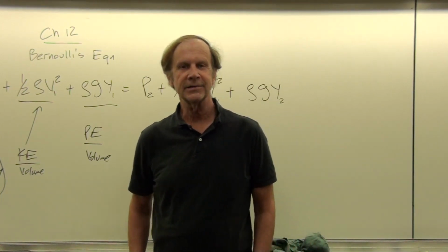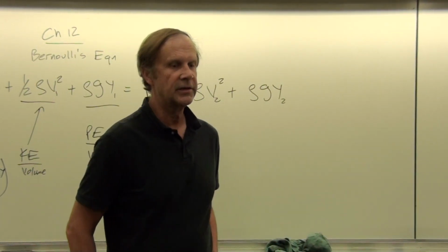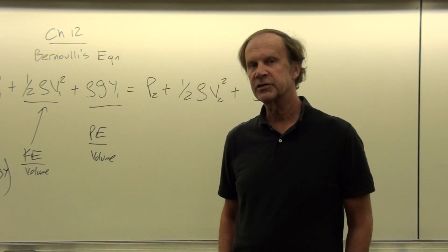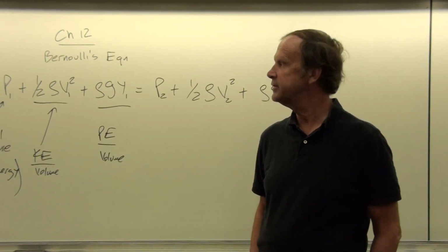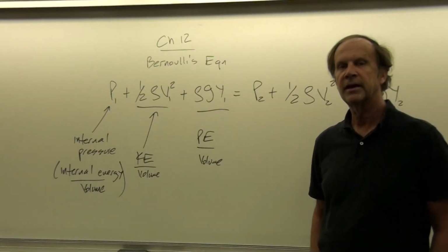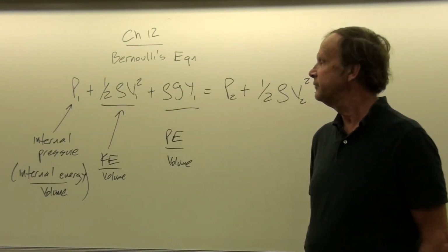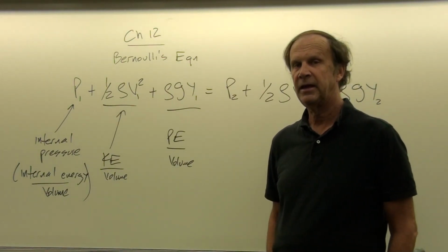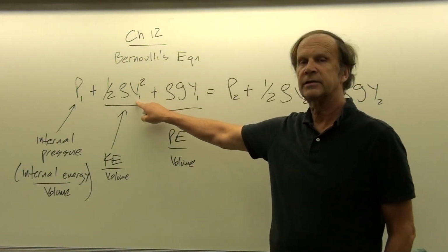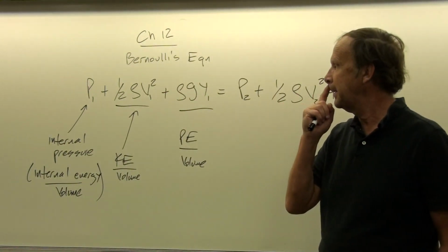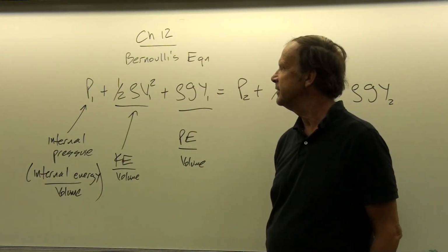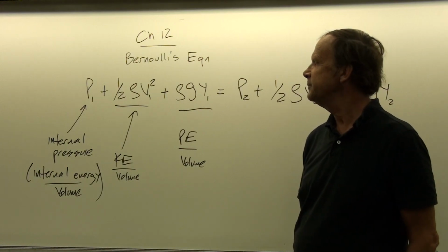Right. Next, I'd like to look at Bernoulli's equation, and this is a more generalized form for the pressure expression that includes the pressure at depth relationship that we had looked at before, but also takes into account the possibility that the fluid medium is moving. And if the fluid is moving, that means that there's a velocity of fluid flow in that region. And so to encompass all of these different possibilities, we have what's called Bernoulli's equation.